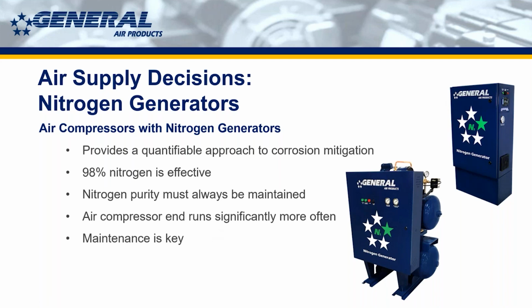You have the compressor maintenance that needs to be done, because it does have a functioning, basically a tank mounted oilless air compressor on them. On the larger ones, it's a tank mounted lubricated compressor. So the standard compressor maintenance must be done, but then there's also the additional nitrogen membrane maintenance, which is pre-filters that are before the membrane. And then there's a whole host of other standard maintenance procedures. But again, if you don't do the maintenance, you won't realize the benefit of the unit. It will not last a long time, okay?